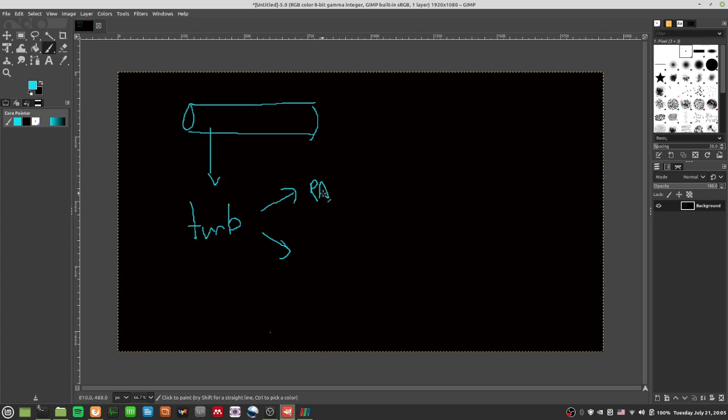RANS, which is called Reynolds averaged Navier-Stokes, gives a time average of turbulence, and it will use a turbulent viscosity, nu t, to model turbulence. You won't see the velocity fluctuations for RANS when you do this sort of turbulence modeling. Normally in turbulence you expect the velocity to fluctuate a lot. In RANS, all these fluctuations are modeled, captured as this turbulent viscosity.